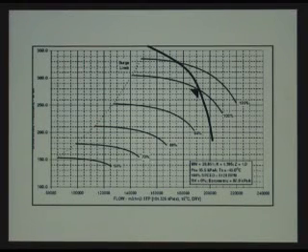And so there are a lot of downstream equipment considerations when we try to evaluate this kind of performance curve. There is a possibility that you could limit yourself to this discharge pressure in the controls, but that only gives you a very narrow flow range. If your process never goes outside that flow range, then it might be an acceptable curve for you to live with.